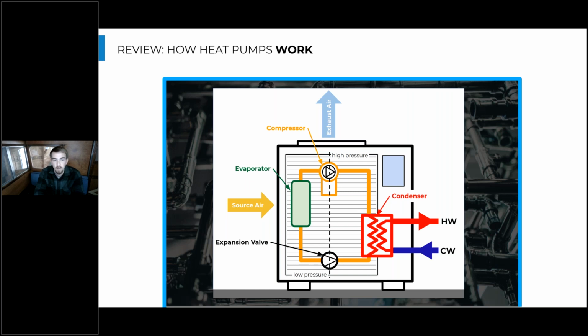I noticed it when I was paintballing. My CO2 cartridge starts to go empty, and then it gets just ice cold because it's had that drop in pressure. It's also having a drop in temperature. So what's happening here is, as this compressor pressurizes this refrigerant and sees this instant pressure increase, we also have a really high increase in temperature, right?